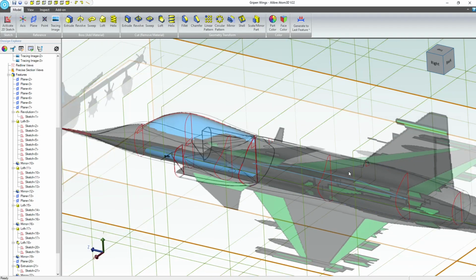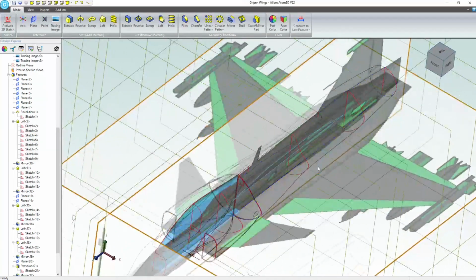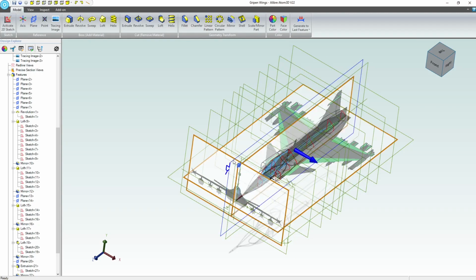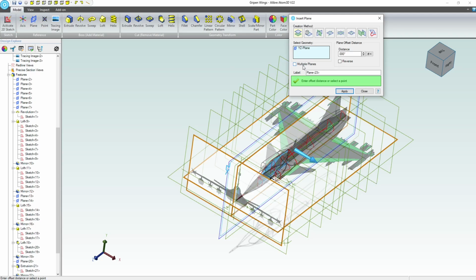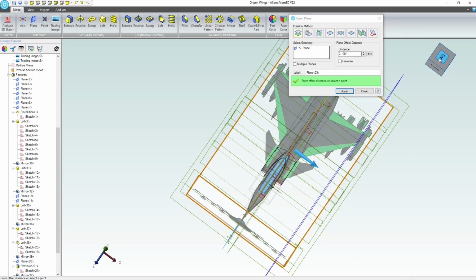All right, so we used 4 sketch elements to make that, and now I'm going to want to make the end of the wing over here, and to do that I would want to make a plane, right? So we could take the YZ plane, and that's pretty close.